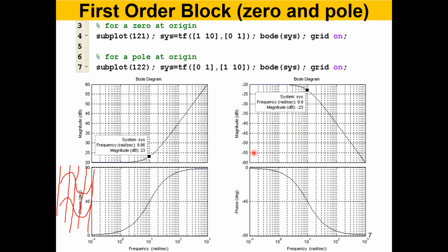Now, on the right hand side, you can see the Bode plot for a single pole at -10. If you send very low frequencies, right, you will see -20 dB gain. -20 dB means weak. It's seriously attenuated. And when you increase the frequency, it will further attenuate like that.